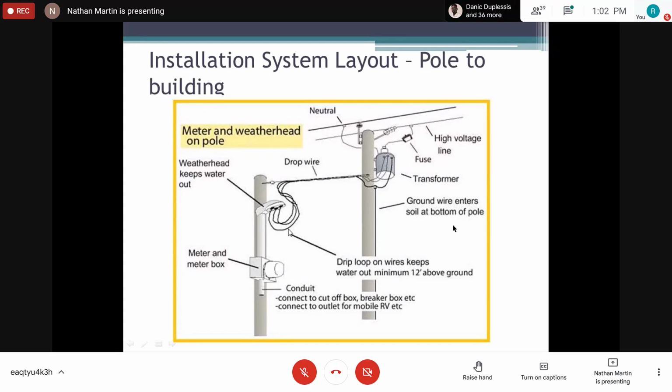Now, one thing to know is that when you are burying cables, you need to have the cable at least 18 inches underground. You need to have at least 6 inches of refined material that is free from debris, free from anything that will puncture the cables, whether you are using SWA or even if you're using conduit. And that is why they use sand, right? Because the sand would have been sieved and all the debris and anything that can cause damage to the conduit or cable is removed, right?